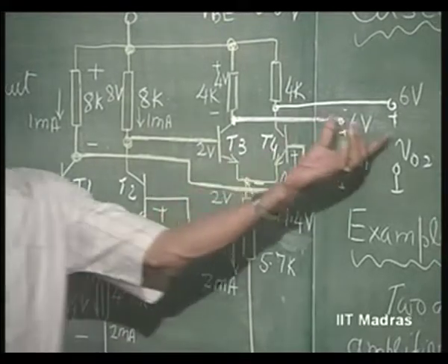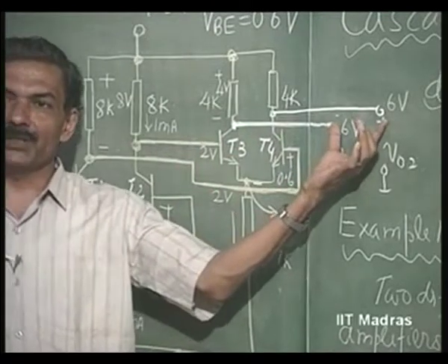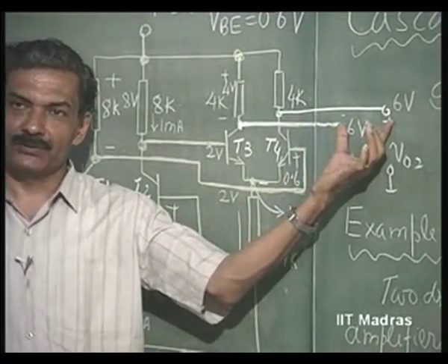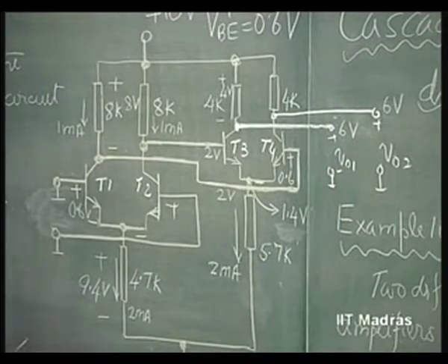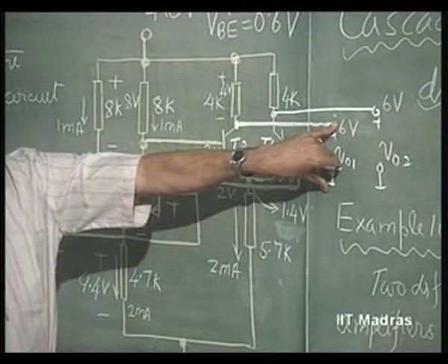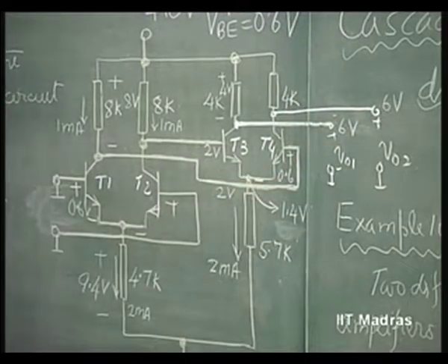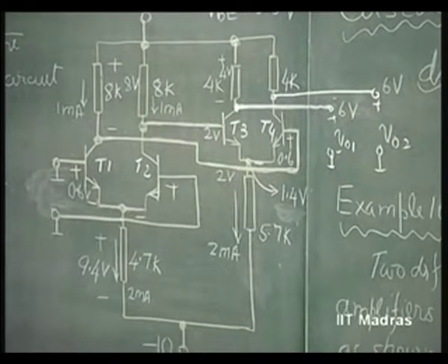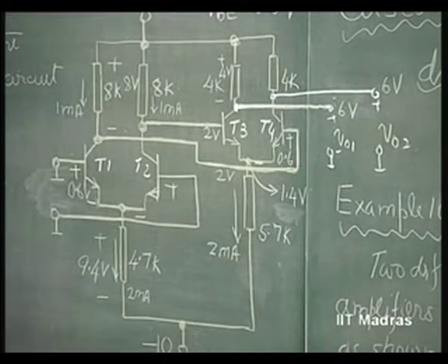So, the difference output is going to be 0 volts. If you take the differential output for a differential input equal to 0 volts, then the output voltage is going to be 0 volts. So, basically for a single ended output you have the offset voltage as 6 volts or quiescent voltage as 6 volts, and for differential output it is 0 volts. Now, what about the gain, etc. So, first let us consider from the input side the input impedance.